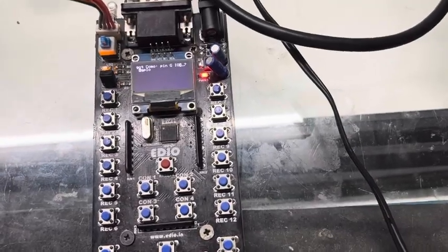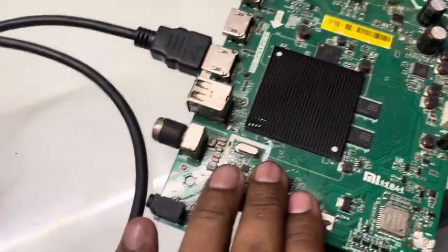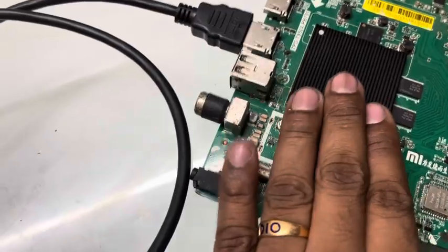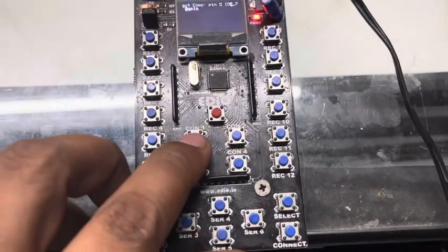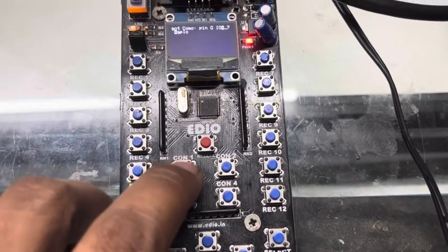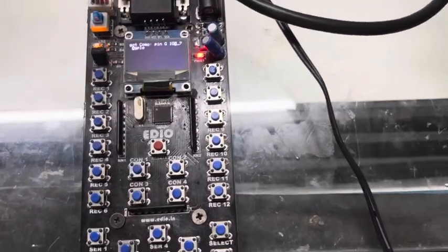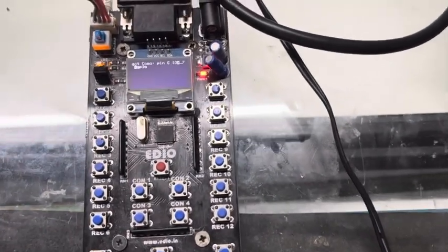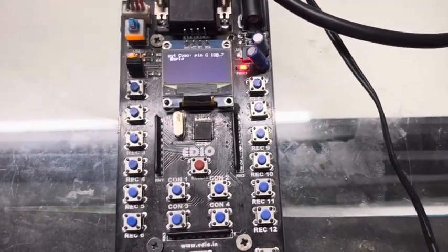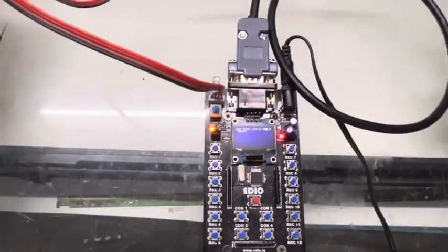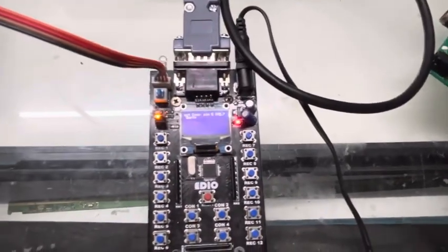That is the one method. For MI motherboards, what we are going to do is put the motherboard into standby condition. Then press the console on button, and it automatically enters the console mode. Then you give the recovery commands. Based on the processor, this console entering process will also change, so you just want to know what processor they are using. This is the main thing.